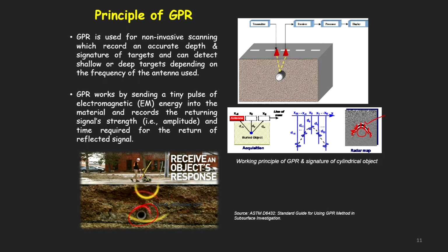This will produce a typical signal as shown here. So, for the pipe sitting here, you can even calculate the diameter of the pipe and also the depth at which it is encountered. So, we can identify the subsurface object as well as the depth at which it is lying, and similarly it goes for these structures also.